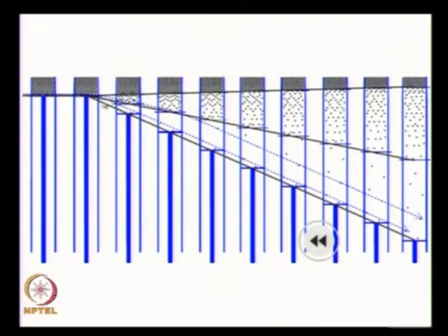What this means is, as it is increasing, I can now say that if my flow is supersonic, you remember this from long back, we said that if the incoming flow is supersonic and the area is increasing, we are going to have higher Mach number. That can also be seen from inside here if we think about the streamlines as stream tube walls. That is the extra information I wanted to give in this particular expansion fan example.